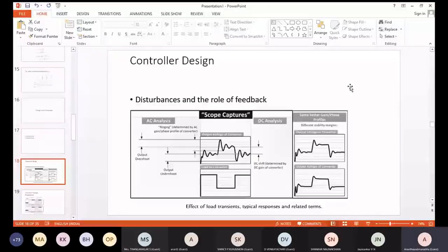Then we have energy storage elements in any power converter. Without energy storage elements, we cannot even think of any power converter. These energy storage elements have inertia. We can say they are elements which contribute to time. That means they will not respond immediately, whereas a resistive element will just jump to any change that you dictate. But an inductor and capacitor will not do it. If you ask the current through an inductor to change now, it will do so after some milliseconds based on the time constant. That means it's an element which has a reluctance. It will not respond immediately.